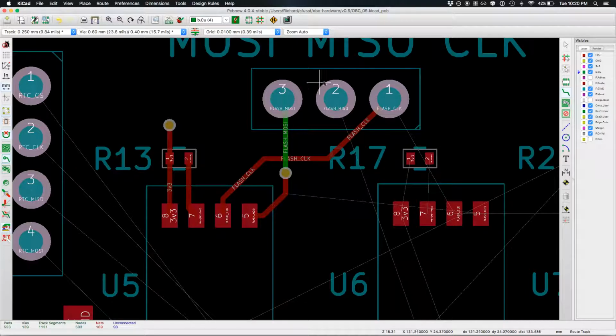When you're going to pin connections on the edge, these you can connect to any layer. So it can be red or green coming into here. But for pads, those have to start as red, and then you can go down to green as you need to.